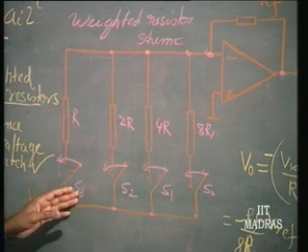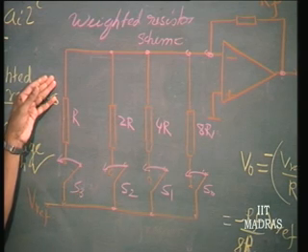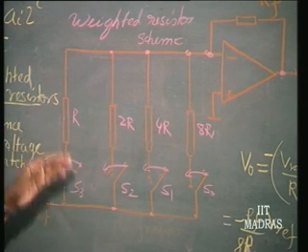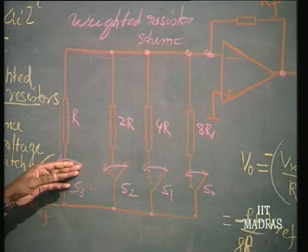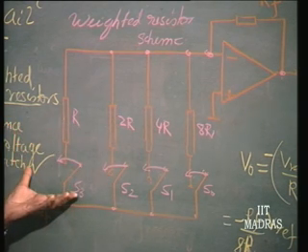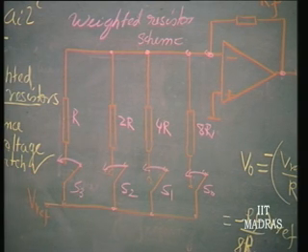When it is off, it will still leak some current into R. So, the on resistance and off resistance of the switch is also going to contribute to the error in the output. So, we have to therefore see how these things can be improved.